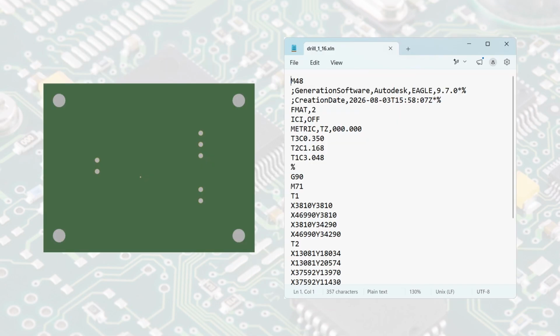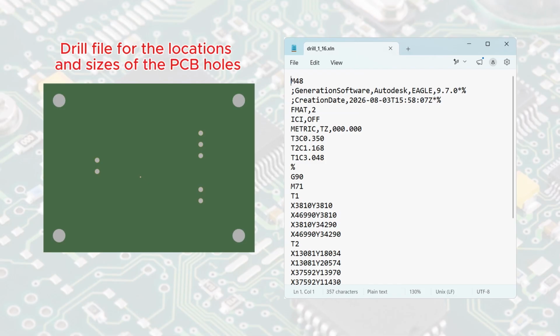To transfer a PCB design from Fusion 360 to the manufacturing process, the design is exported as a collection of Gerber and drill files. The Gerber profile file defines the PCB's overall shape, dimensions, and any internal cutouts, providing the information required for board routing and machining during fabrication. The drill file specifies the locations and diameters of all holes, including component mounting holes and vias, enabling the manufacturer to accurately drill the PCB before subsequent fabrication processes.